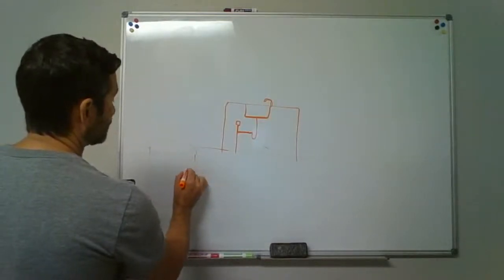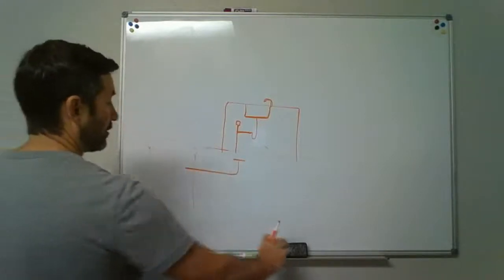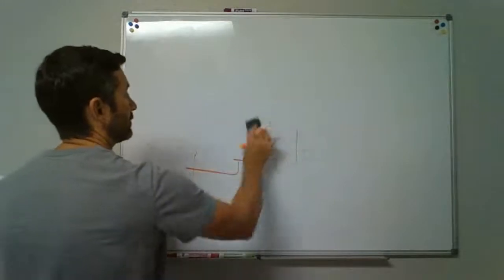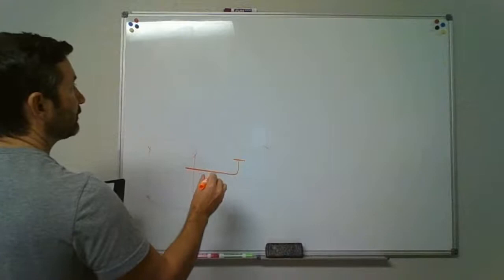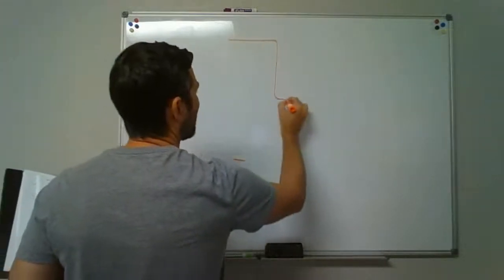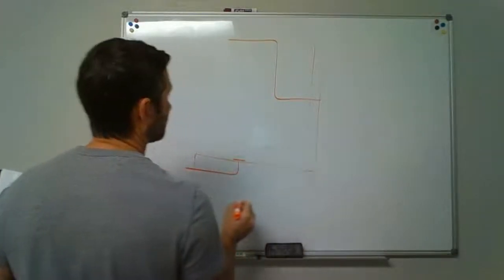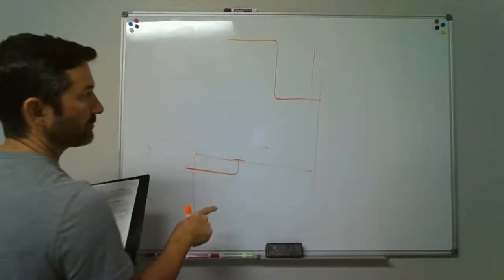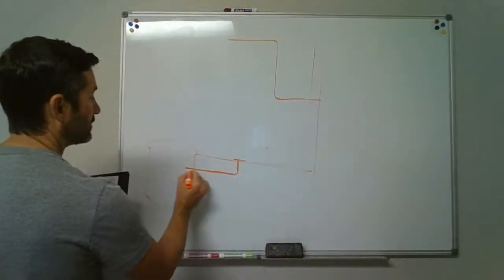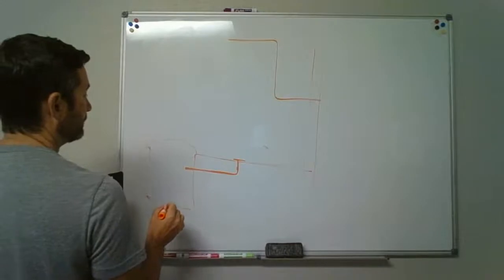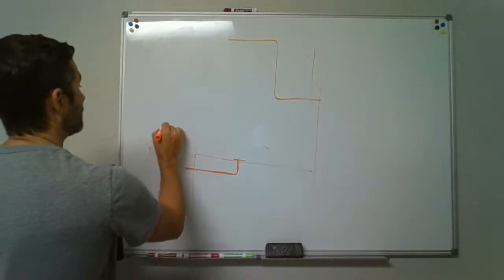So if we had a sub drain that comes over and maybe it's catching a bathroom, we've got a toilet and everything else, but this is below, and this is below where everything's going to flow. Here comes the main drain. It goes out and then out your wall. And down here you are in the basement. You're like, well, I want to put a bathroom in the basement, but my drainage is going out up here. So you take your drain and dump it into this tank. The tank has a pump down in here. It will pump things up.